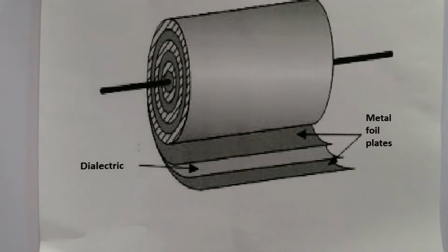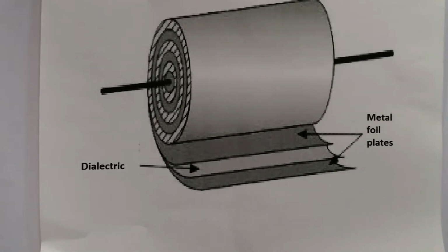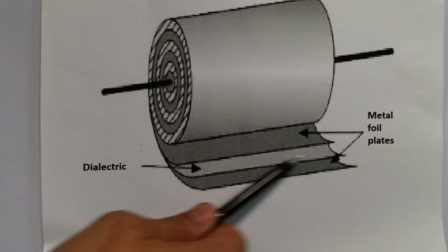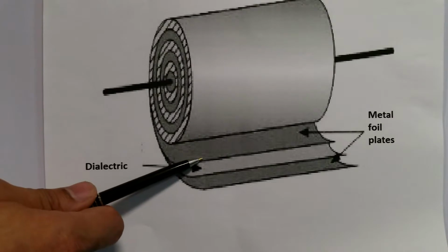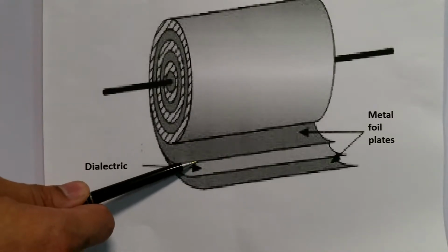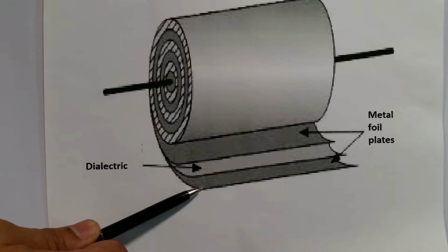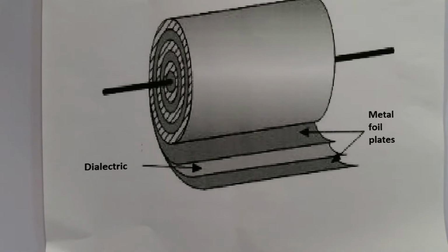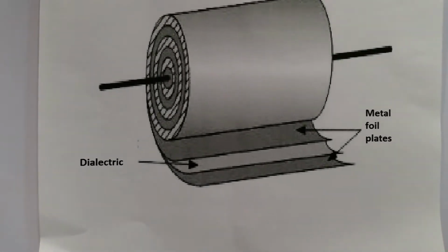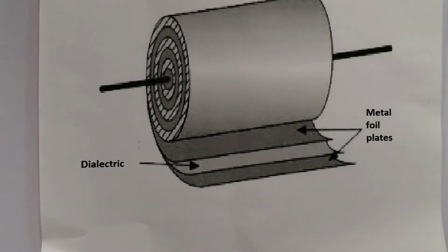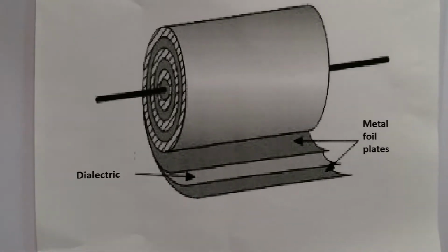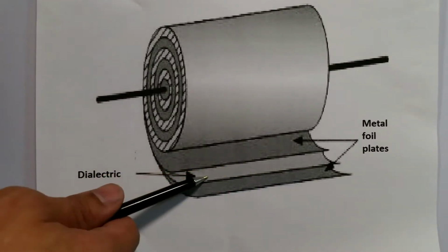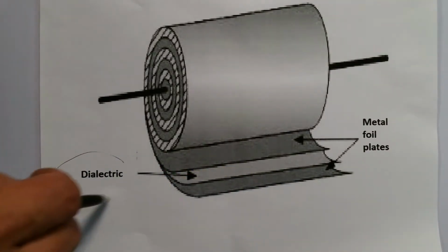As a matter of fact, if you want to make your own capacitor, you can simply take foil paper on one side, electrical tape in between, and then more foil on the other side. But the catch is that the top foil cannot be touching the foil on the bottom, so the foil is going to have to be smaller than the actual electrical tape. It's not going to be the best capacitor, but it will be a capacitor, especially if you make it very big or very large. Remember that the barrier in the center is always called the dielectric. That's the proper terminology.